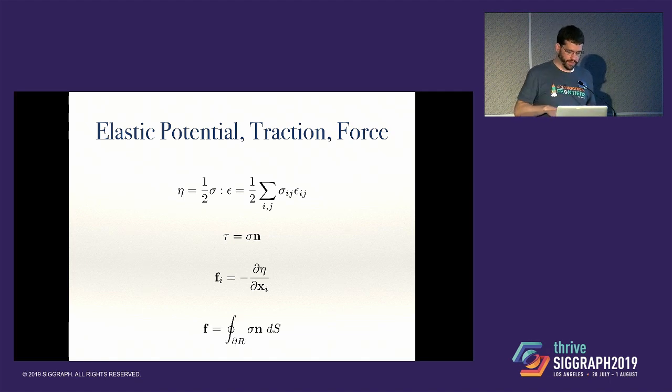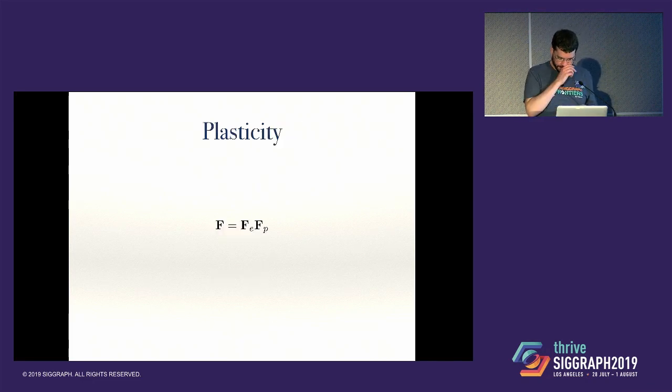You can also characterize forces as being the integral over the boundary. Using the divergence theorem that Tamar was talking about earlier, you can characterize them as the integral over a boundary of the stress times the normal at that point of the boundary.